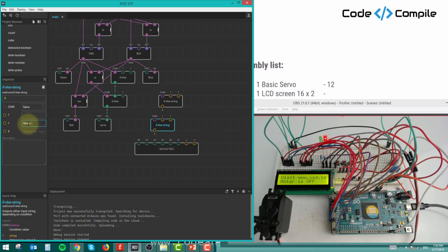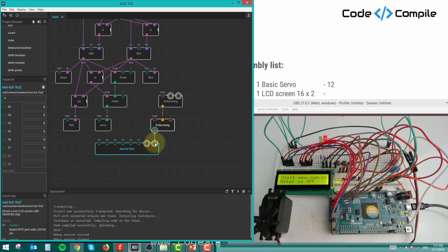All right, so the same function, when this string is false, we have to write motor is off. Okay, when this string is true, we have to write motor forward or motor is clockwise. So I will write in the true, motor clockwise. I have to make sure I don't use more than 16 letters, and in the false, motor anti-clockwise. Okay, well, I need to count. I think this is okay, but I can remove this. That's fine with me.